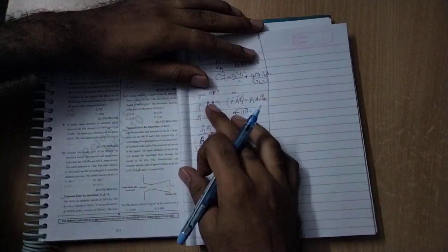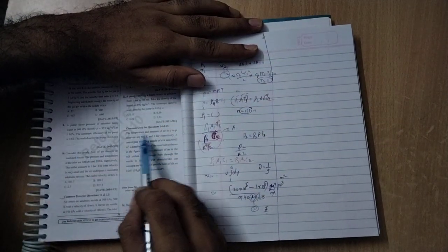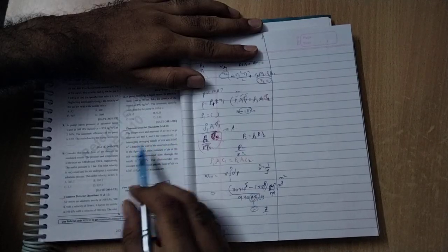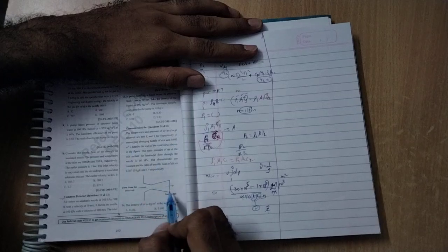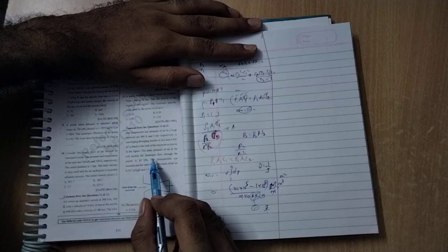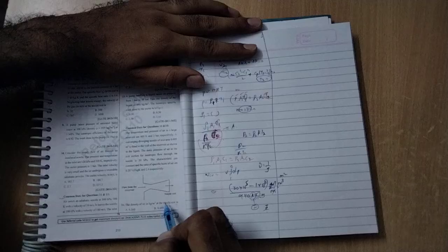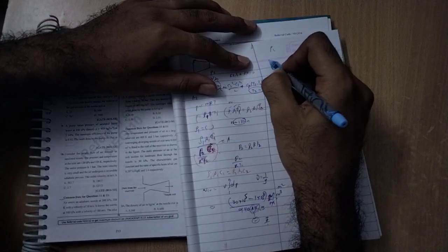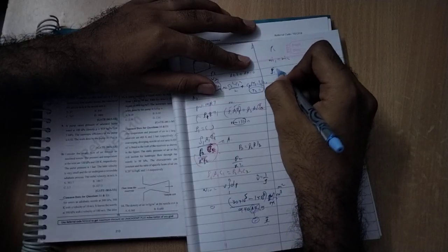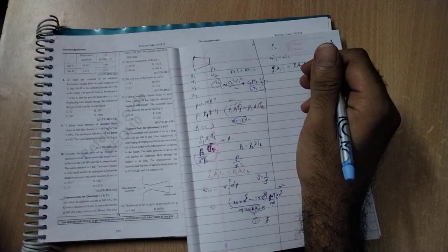They have given a convergent and divergent nozzle. The temperature and the pressure of a large reservoir at inlet are 400 K and 3 bar. The exit area is given, the static pressure at the exit is also given, and the characteristics are also given. So they are asking for the density at the exit, rho 2. Since m1 equal to m2, rho 1 A1 C1 equals rho 2 A2 C2. But we don't know the velocity.